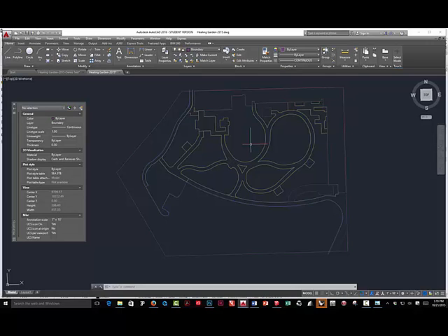The other thing you want to make sure is, and in this case, I don't think anything in here is, when we do the lines as a separate thing, some of those actually had elevations in them for beginning points and end points. And so one's at 0 and one's at 1091 or whatever, and it doesn't work very well because you get a line that goes way up in the air. So you want to make sure all these surfaces are two-dimensional. The contours, we don't want to touch them. We want elevations. But these other things, we want two-dimensional. We're going to create surfaces out of them and drape them on a landform, as you'll see in the next tutorial. So once I have this isolated, I've exploded the polylines so that they're arcs and line segments.